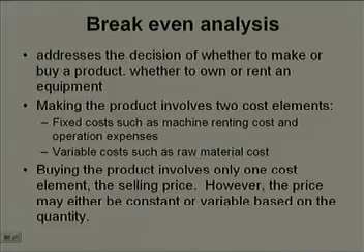Now, if you see the application of break-even analysis, its prime area of application is to analyze making versus buying a product, whether the company should make a particular product or whether they should buy it. Similarly, the other application area, as far as a construction company is concerned, is whether to own a particular piece of equipment or rent it.